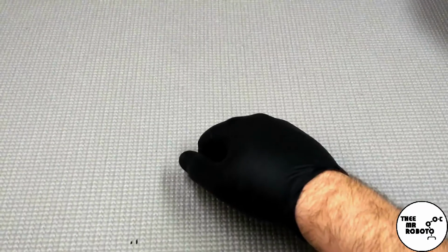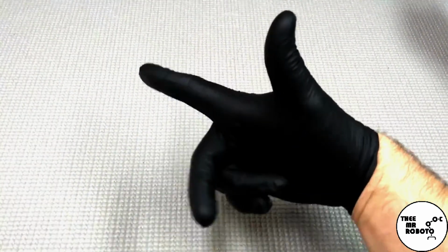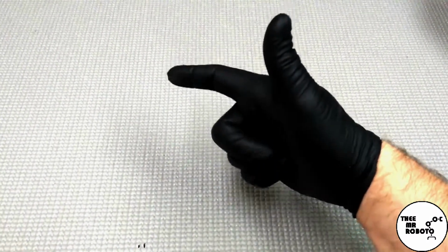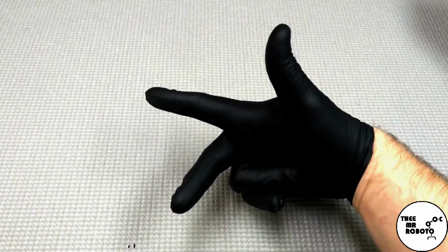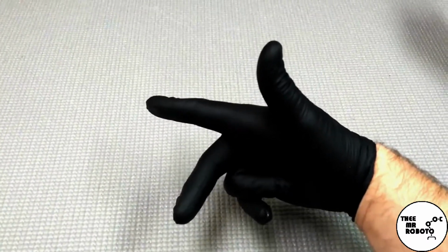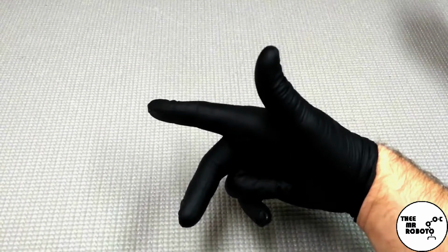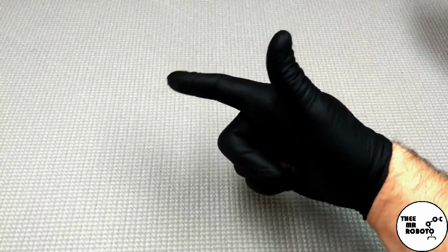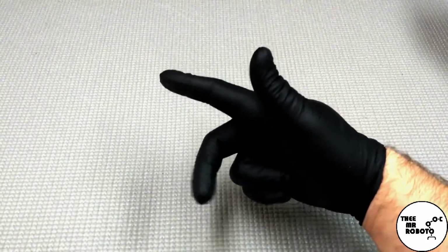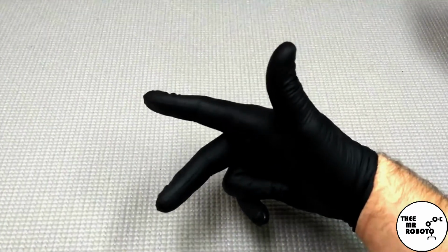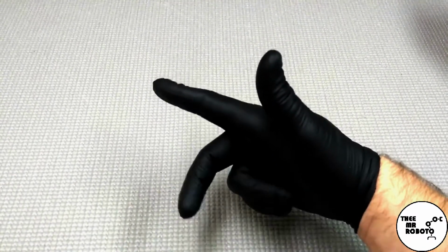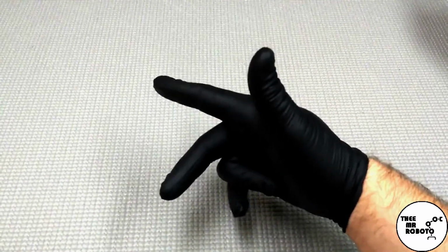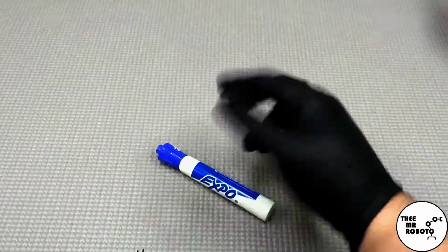And to define the coordinate systems, industrial robots use the right-hand rule. The right-hand rule is simple. You make a pose like this, like you're pointing at someone. You stick your middle finger out and you put your thumb up. Okay, so the X direction motion is always going to be this finger. The Y direction is always going to be the middle finger, and the Z is always going to be the thumb, right?